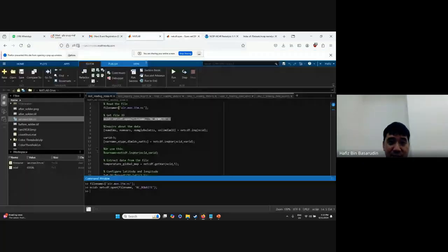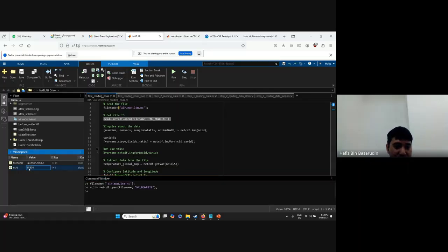Now let's have a look at MATLAB again. There we go. Don't worry about this. This means that I'm not going to rewrite the data. I'm just going to download and extract the data. So netcdf open. And so my data is now open. Okay, but now you have another problem. My data is now recognized in MATLAB, and the ID is 65536, assigned by MATLAB for this data that I downloaded.